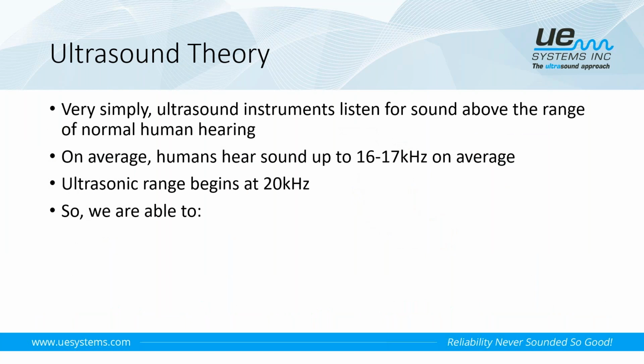So a little bit on the technology, what it is and how it works. Similar to the way an infrared camera sees what you can't see, an accelerometer feels what you can't feel, ultrasound instruments listen for sound that we can't hear. So there's things taking place within a typical plant facility that we can't hear just simply because of all the other plant background noise. But with ultrasound, we're able to hear these sounds above all that ambient or plant background noise.